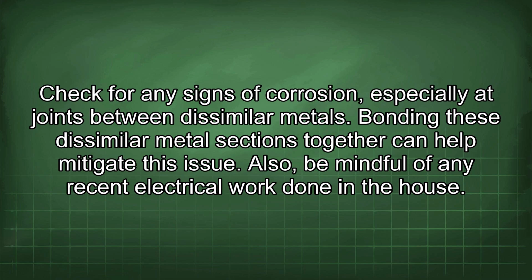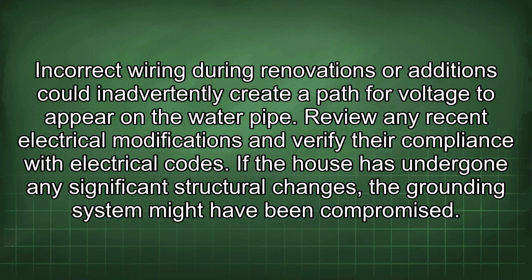Also, be mindful of any recent electrical work done in the house. Incorrect wiring during renovations or additions could inadvertently create a path for voltage to appear on the water pipe. Review any recent electrical modifications and verify their compliance with electrical codes.